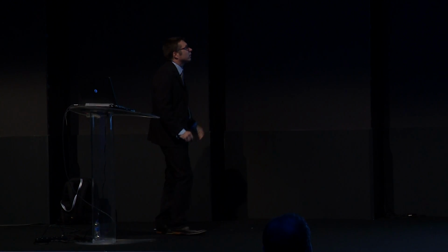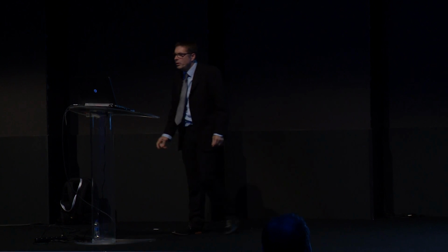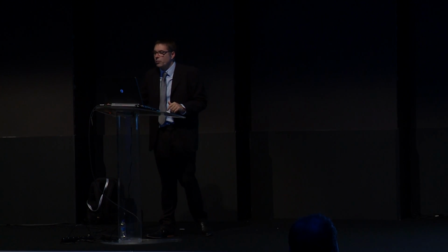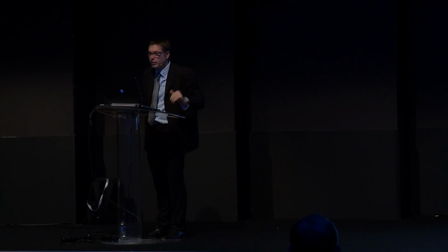Wait, I will use the library to show you what we can find in this library. I go in level here, and you've got different kinds of nodes to create level. I will use, for instance, elevation and name. You see this node, you've got two inputs. First, elevation, of course, and the name. Elevation will be the altitude, if you want.